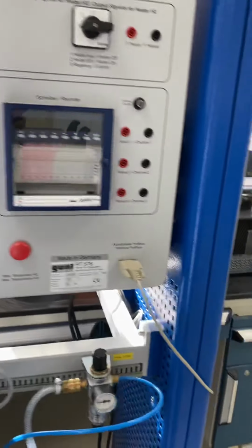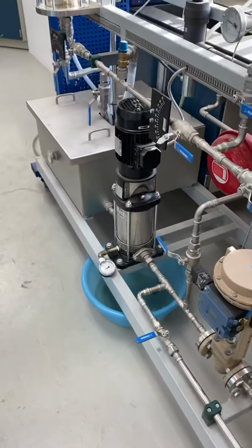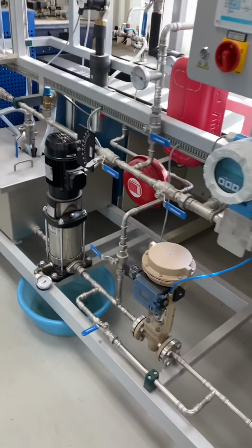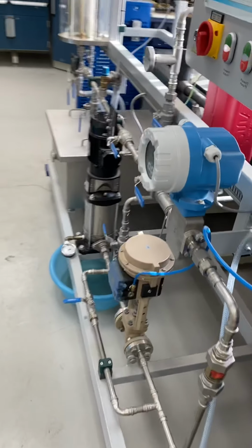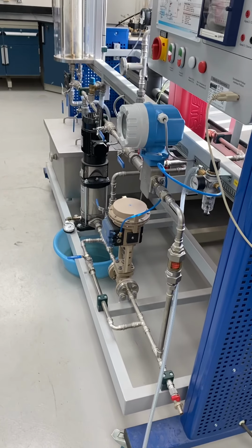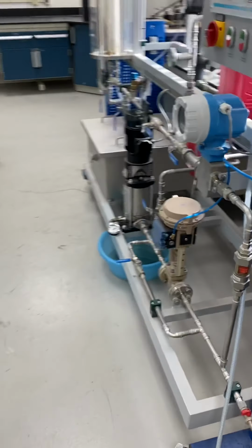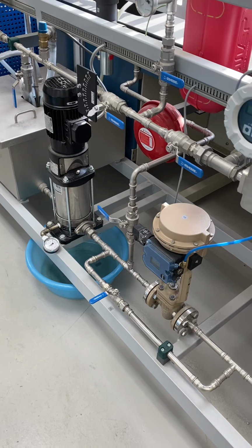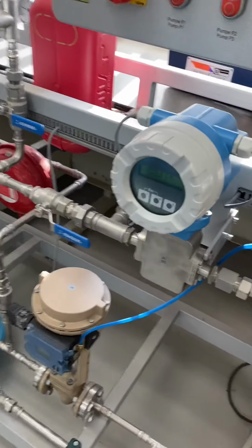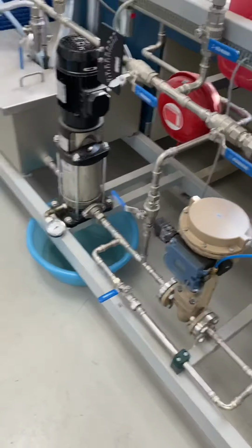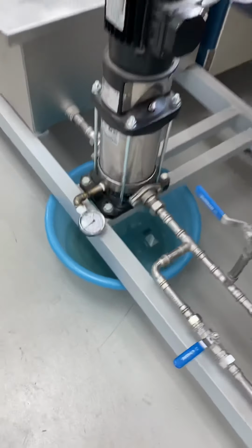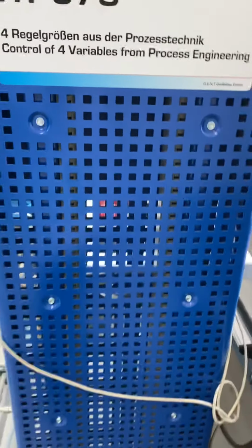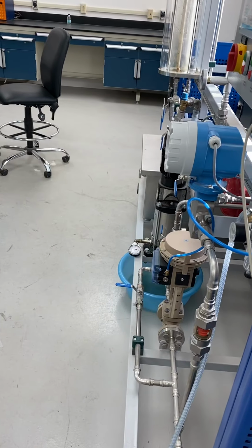So what we can conclude is that with the fixed speed pump and control valve configuration, there is an inverse relationship between the discharge pressure of the pump and water flow rate, or the discharge flow rate of the pump. The higher the flow rate, the more you increase water flow rate through the system, the less discharge pressure obtained, as we said before, at the discharge of the pump.